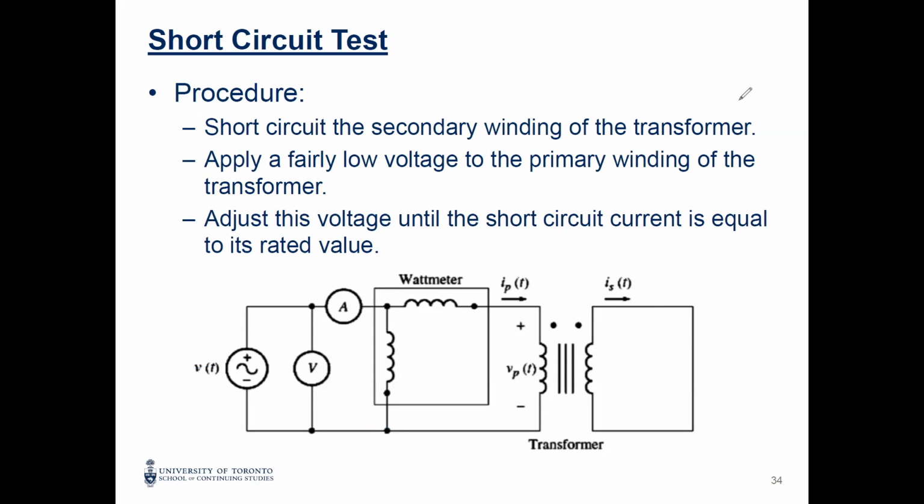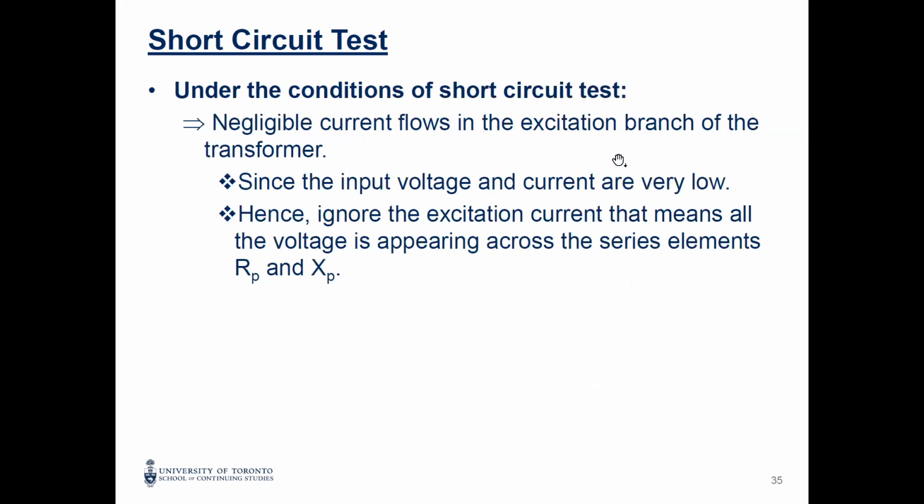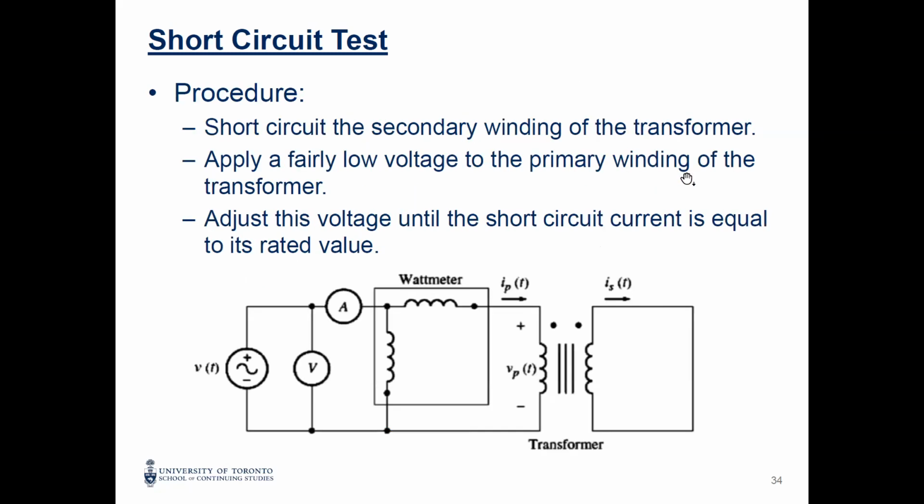Okay, next we have the R and X equivalent. Let me first tell you why we have the R and X. For this current, we said the current will reach the rated current, right? And this is the equivalent circuit for the transformer. You have the RC and XM or JXM. Make sure that you include the J during your calculations.